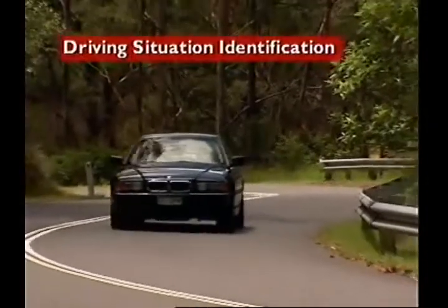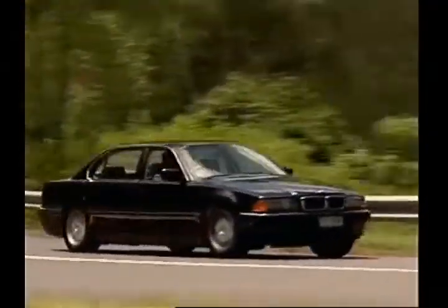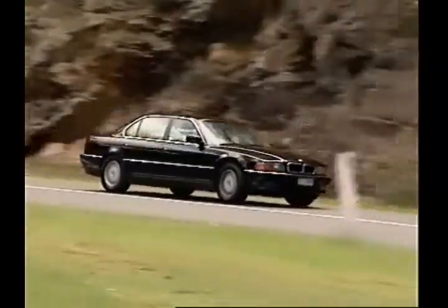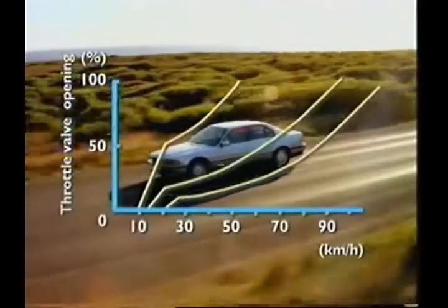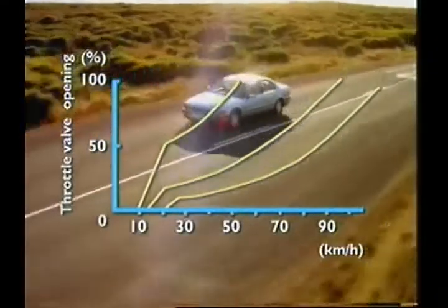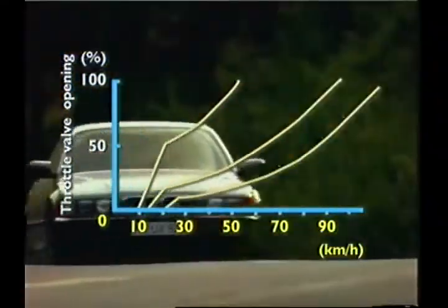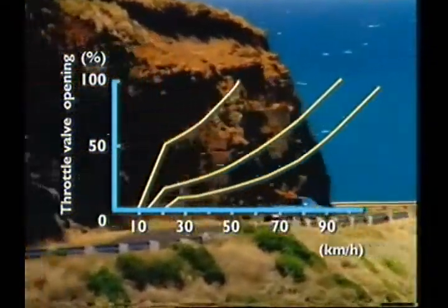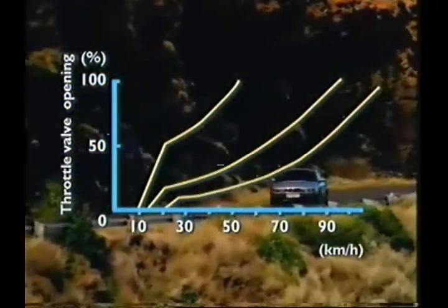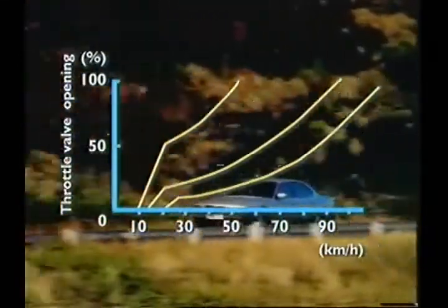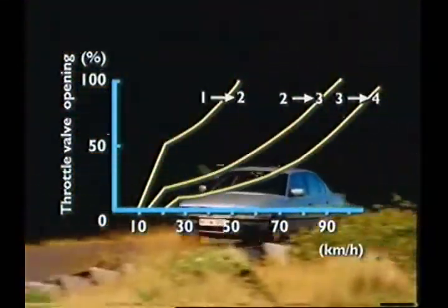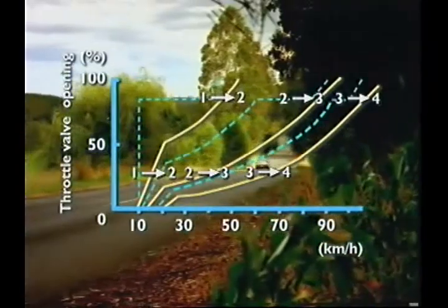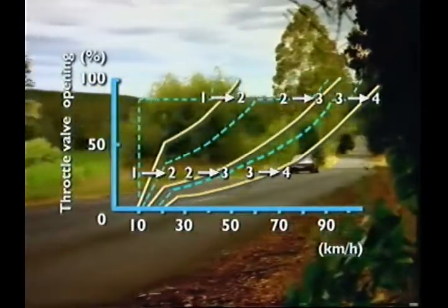In specific driving situations, it can be beneficial to select a gear not normally selected in a shift program. A normal shift program characteristic initiates shift changes according to road speed and throttle opening angle. Shift characteristics are arranged so that upshifts are triggered by an increase in road speed or by reduced throttle opening. Downshifts occur when the opposite situations apply.